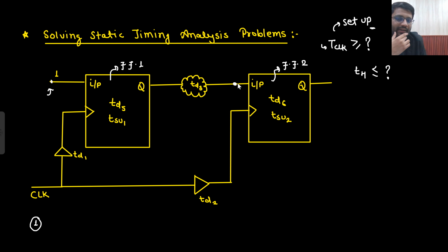Now my target is that I need to reach this point. In this circuitry, I need to start from the clock and reach this particular point. So from where is it coming? It is coming from the output of this guy. How is the output of this guy coming? Output of this guy is coming from this input. Now this input is coming from where? This input is coming from this Q. And from where is this Q coming? Like if the clock edge would come, then some Q output would be there, that would be fed to this combination circuit, that will give some output, and then the input will be set up here. It could be either 0 or 1. Is that understandable to you?